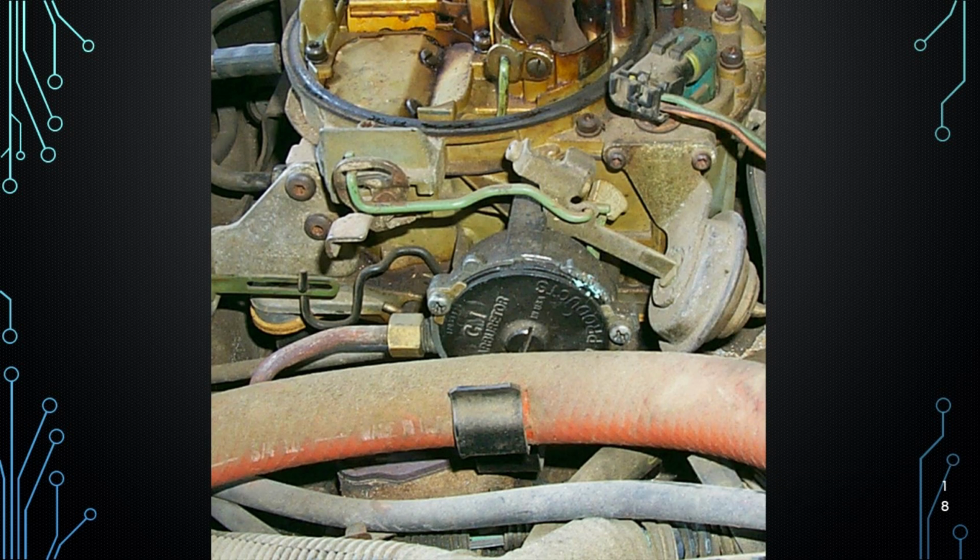The black cylindrical piece in line with the heater hose is the choke pull-out. It uses vacuum to gradually open the choke on cold starts. The gray chamber with a lever is the mechanical or thermostatic choke housing itself. Inside, a bimetallic coil or thermostat opens the choke as the engine warms. Together they regulate airflow and mixture during warm-up.